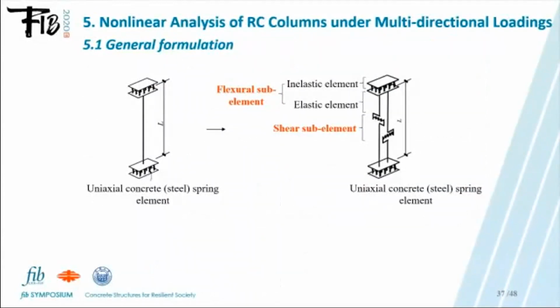Part 5, Nonlinear analysis of RC columns under multi-directional loadings. Based on the experimental results, it can be assumed that the load carrying mechanisms for an RC intermediate short column include flexural and shear modes.